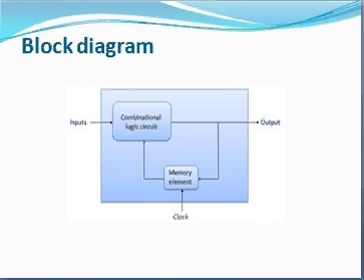This is a simple block diagram of a sequential circuit. Here we have a combinational logic circuit, and the output of the circuit is fed back to the combinational logic circuit through a memory device, and the memory device is enabled by a clock input.